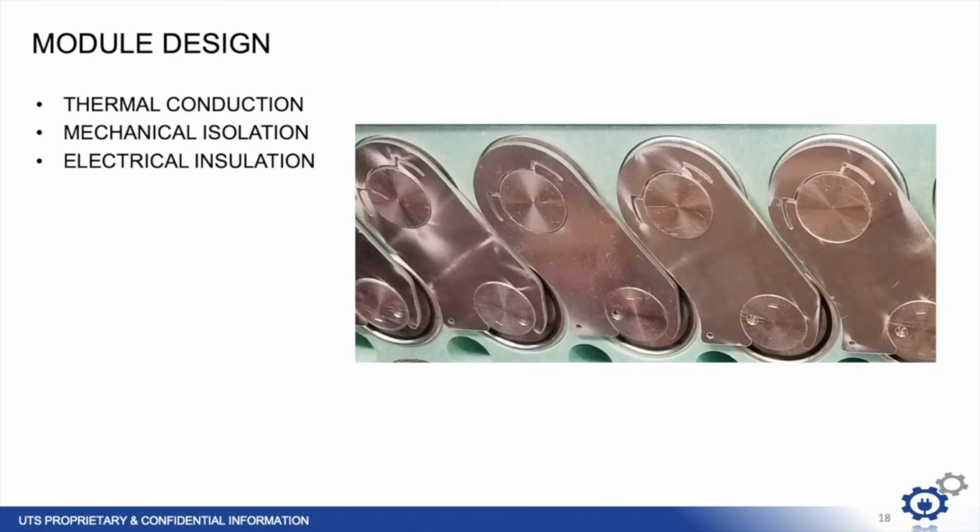So again, for a module, we start by taking any number of capacitors. We then apply bus bars to create our series and parallel configurations. We somehow hold the array rigidly together as a unit to avoid loading the terminal to bus bar contact, and of course the cell crimps too. But next we have to do three things. 1. Achieve a thermal path to ambient. 2. Achieve the necessary mechanical isolation from the housing. And 3. Achieve the required electrical isolation to chassis. Thankfully, achieving all three of these requirements is not impossible, even though they tend to be somewhat mutually exclusive.